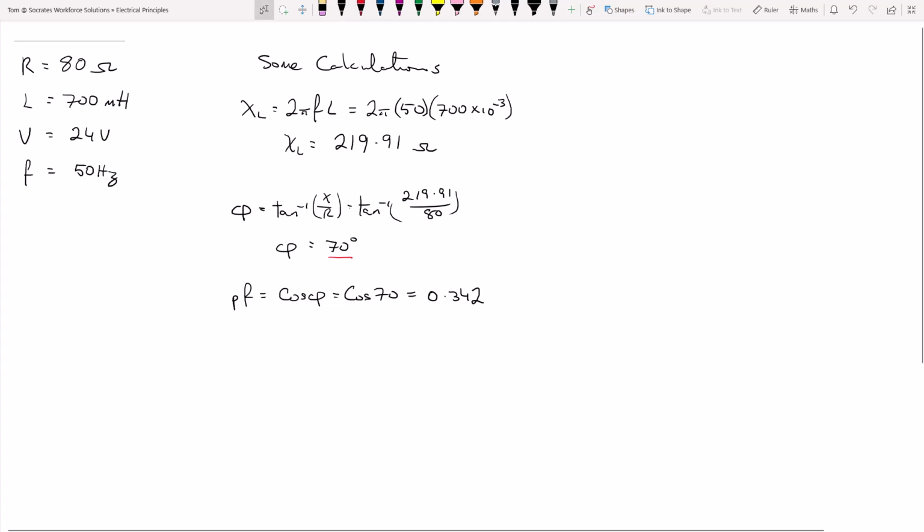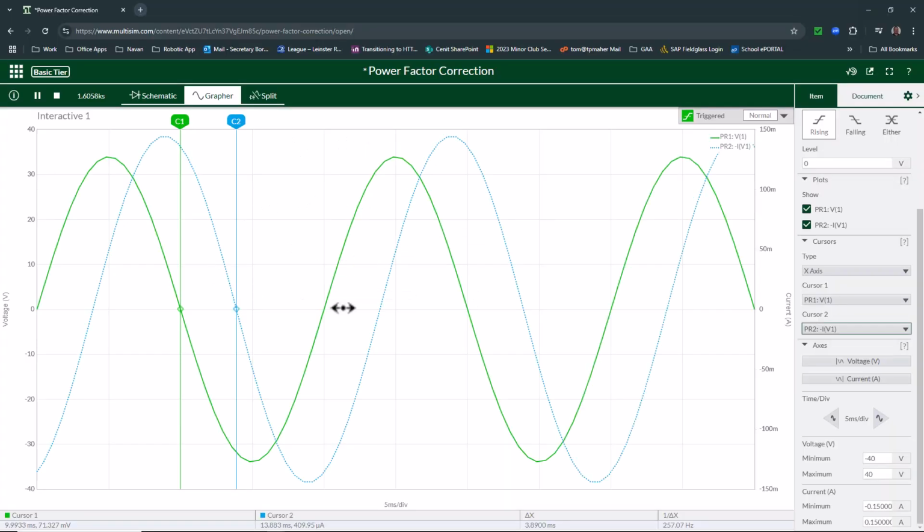Okay, so using the scope, we can use a ratio. So on the sine wave, I suppose let's talk about that for a minute. We know on a sine wave that going from 0, positive, negative, and back to 0 again, that's 360 degrees across the sine wave. Okay, and it doesn't matter what the frequency is, one full sine wave is always 360 degrees. So what we want to do is measure what portion of 360 degrees is this angle here.